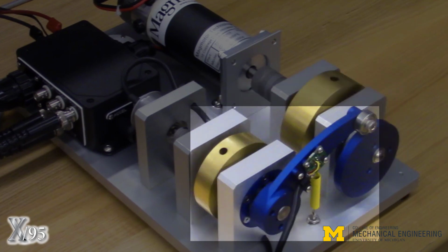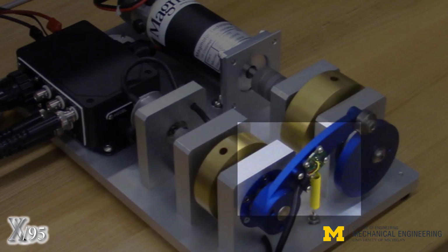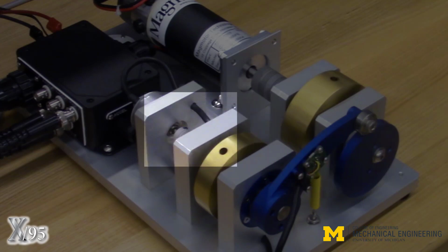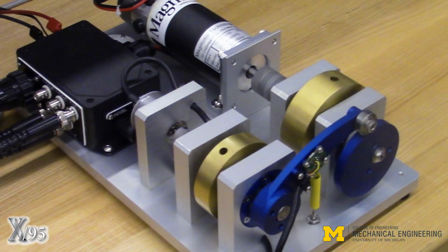A spring-loaded cam follower contacts the cam with a roller bearing and pivots about a parallel shaft containing a secondary flywheel. The cam follower dynamics may be measured using either an accelerometer or an RVDT for rotary position, the latter being the default.